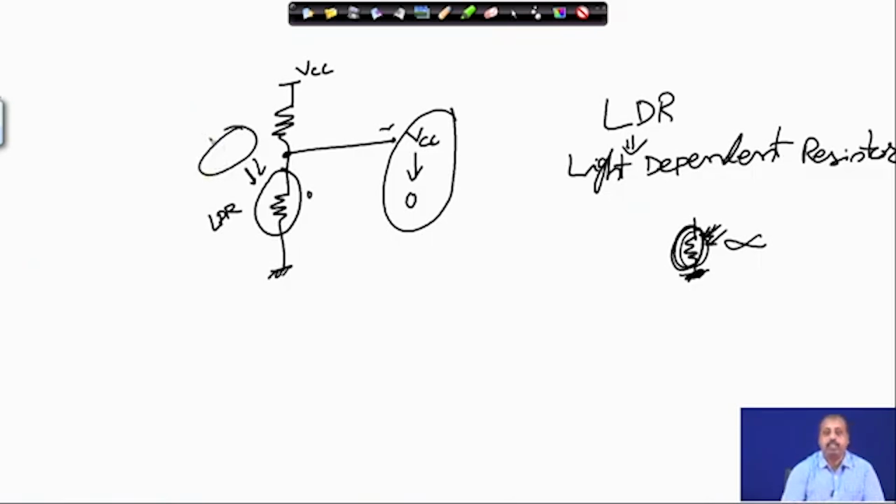There are many such transducers, like pressure transducers, different types of sensors, gas sensors and other sensors that we have. They all come under the heading called transducers. Now, these transducers may be linear or non-linear. A linear transducer means that the electrical signal produced is proportional to the amount of excitation that you have. So, ideally I would have a behavior like this.